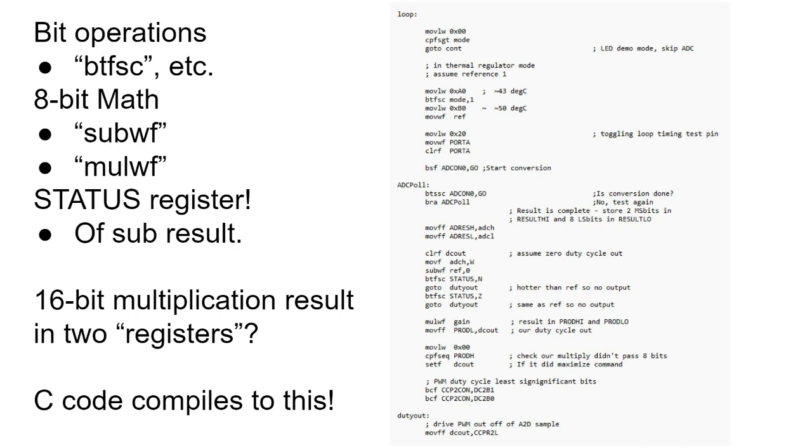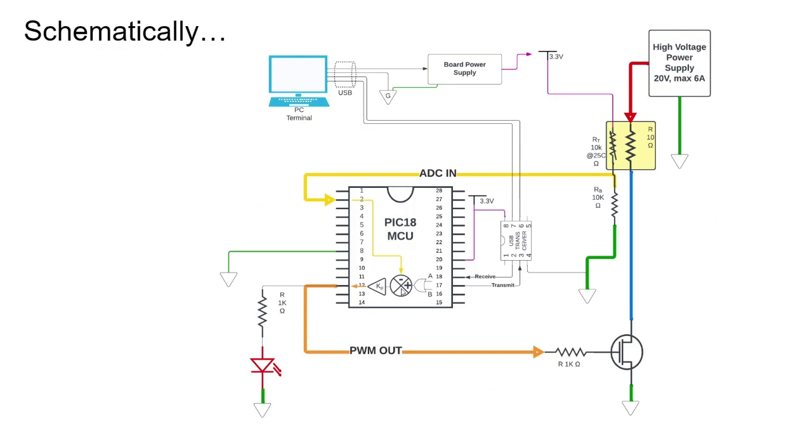And in fact, this is what all your C code, like I said, compiles down to. You start to think about moving data. You're moving data from here, putting it there. And that's what's happening. So I happen to only be using the upper 8 bits of this conversion result, throwing away 2 bits of precision. I'll explain that in another context. Moving it there, here's our subtraction from our reference signal. That's our subtraction from our reference signal occurring there.